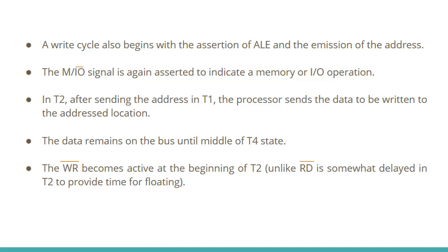Alright. So when the address latch enable signal becomes high, it will indicate that there is a valid address available. This valid address will be available on the 20-bit address lines, which comprise the A19 to A16, that is address bus status lines. The higher order bits will be available on the A19 to A16 address lines, and the lower order bits of the address will be available on the A15 to A0 lines.